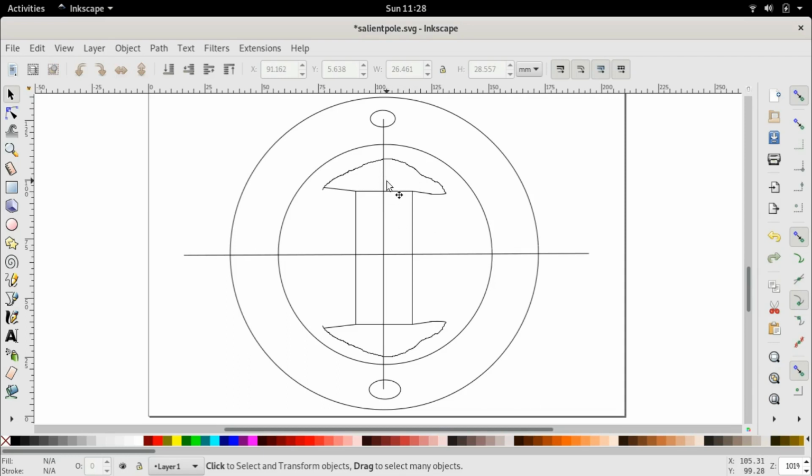In the case of a cylindrical rotor, we had mimicked something very similar to this. So we said that we can consider two rotor slots diametrically opposite each other. In the case of a salient pole rotor, we have to now think, how do we wind the rotor so as to produce a flux? Now, if we consider such a rotor, that is a salient pole rotor, we would like to wind the rotor coil in such a way that it produces a flux that passes through the rotor. Alright, so we can think of various ways. For example, we can say that